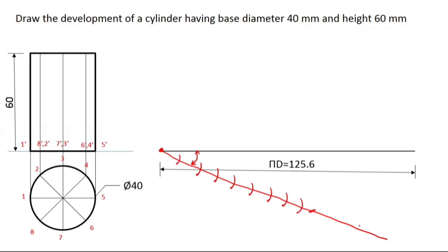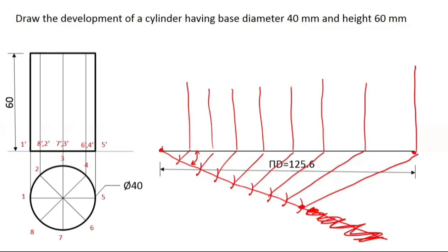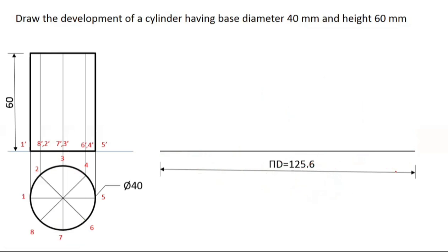And now erase that left out part. So this part should be connected with this part like that. Then set the drafter over here and draw all the parallel lines like that. These lines should be parallel to the last line. And now from these corners draw these vertical lines. Because I am drawing freehand, it looks like the parts are not equal, but they would be equal with the drafter. So that line would be divided into 8 equal parts.